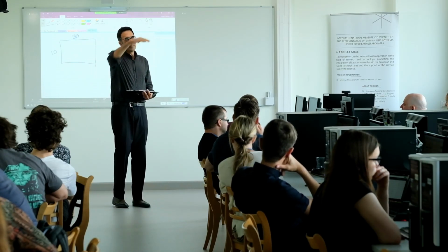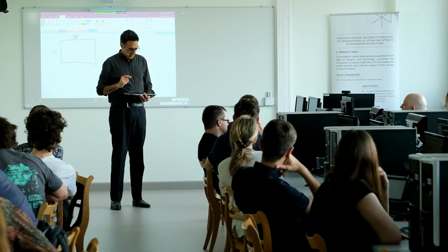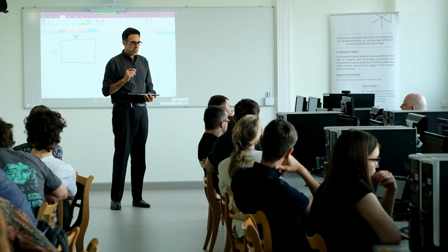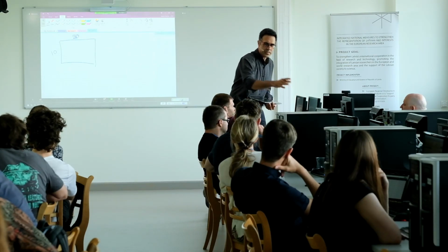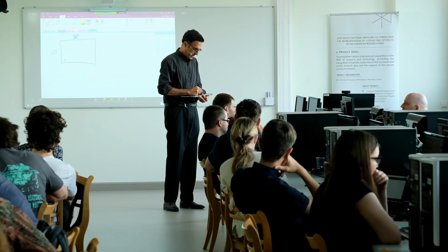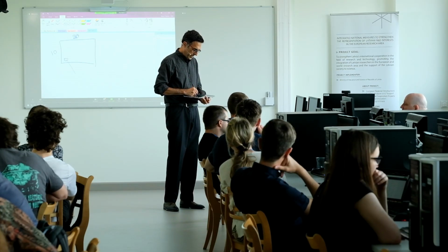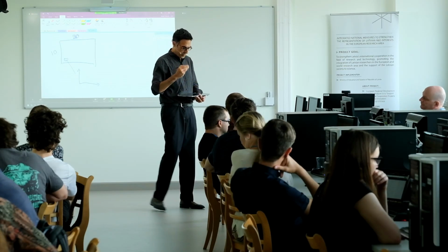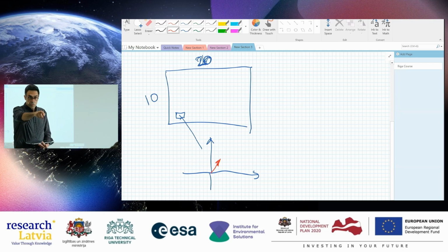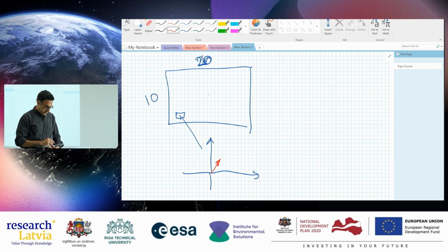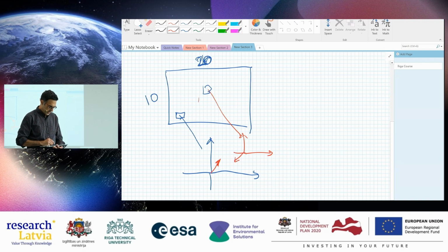What will a radar wave now do if it interacts with this particular pixel, or this resolution cell? Well, what we could do is try to figure out for each little element in this pixel how it would react. So let's take maybe this computer screen over here. Maybe this is one little reflection. So for this screen, in this complex valued coordinate system, I have a certain vector. Let's draw that in red, maybe this little vector, from that computer screen. Maybe from you there is also a reflection, stemming from the location over here, and it has a different angle. So maybe that is this little vector.